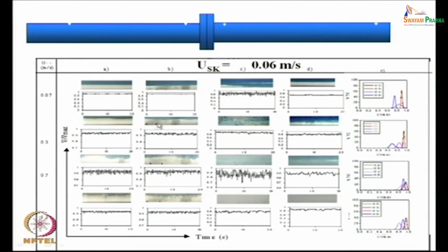So, from distinctly stratified we obtained a 3-layer flow pattern. Then again in this particular case, it was sort of a plug or a dispersed situation, but where the plugs were concentrated only on the upper portion of the pipe. From there instantly what we got? We got a homogeneous dispersion of the two phases, kerosene dispersed in the oil phase. So, therefore, we found what the orifice did for low viscous oil water flows, they served to homogenize the mixture.